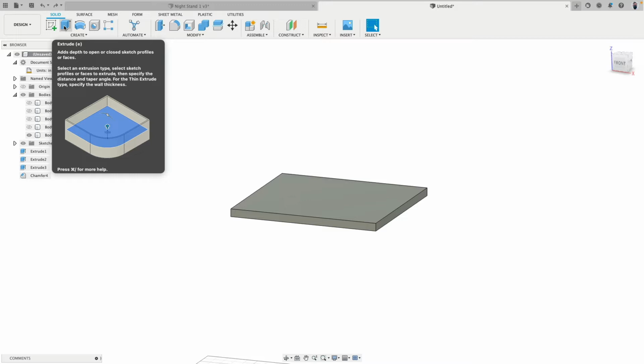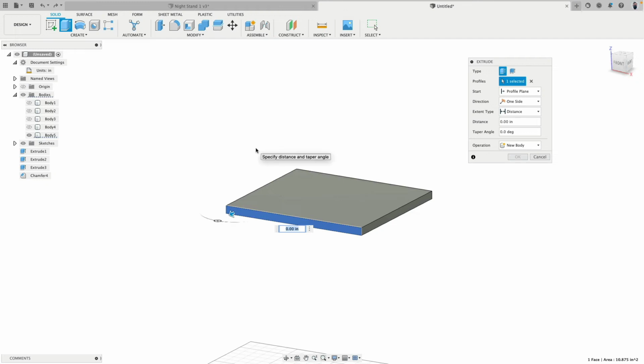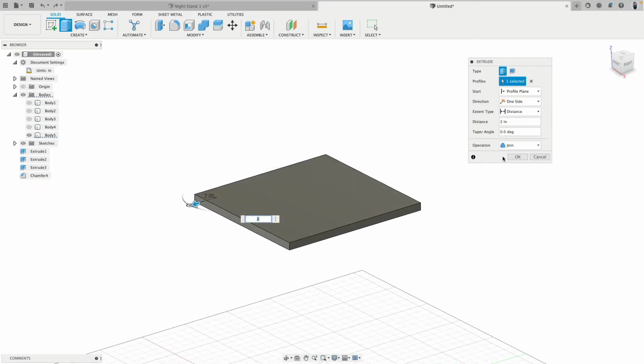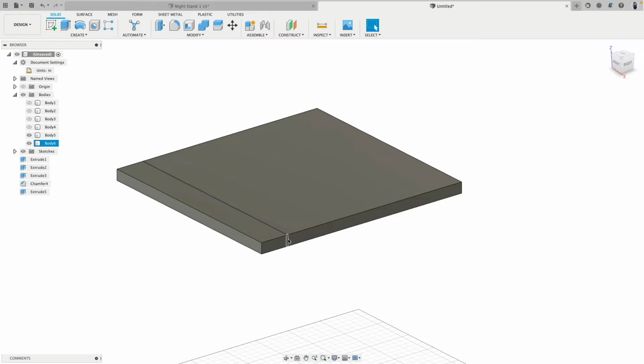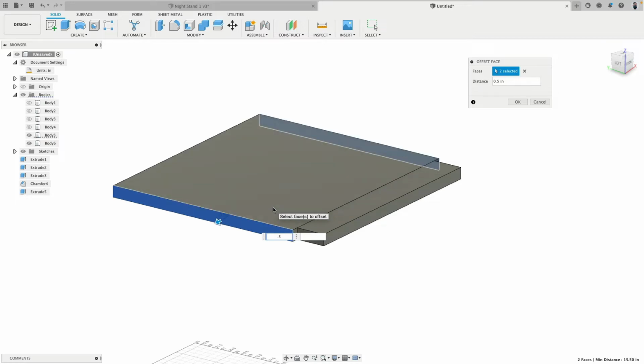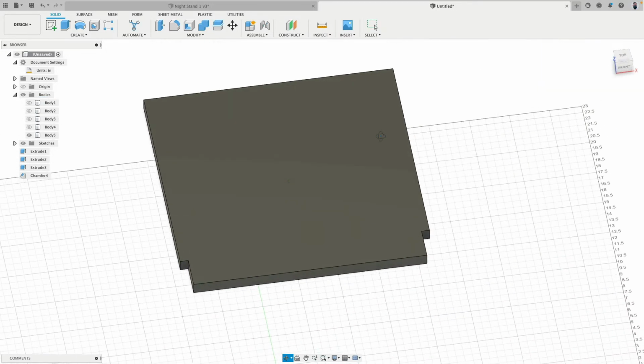So what I will do now is I go to Extrude, select the front. I remember this was 2 inches. So extrude the front face by 2 inches, but as a new body. You see now here I have still this edge, and now I can go ahead and just extend this, and then these 2 pieces I join together. Keep tools off. Yeah, look at this.